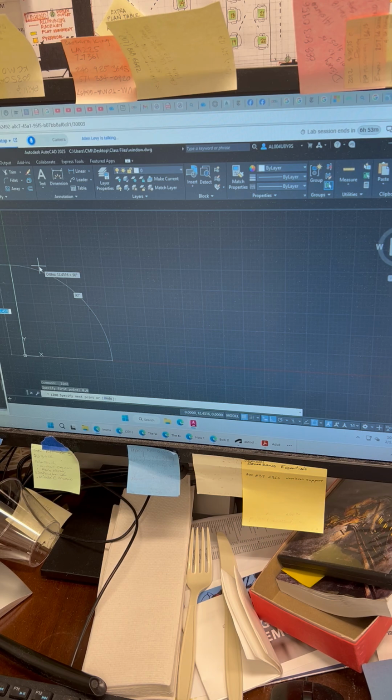All right, once the line command is started, at your heads-up display, at your dynamic input, you're going to enter in, and I'll just say it all in one breath right now so you understand where we're going. I want you to type in 0, and then a comma, and then a 0, and then hit enter. So 0, comma, 0, and then hit enter. And that starts a line at exactly that 0, comma, 0 coordinate, the origin.